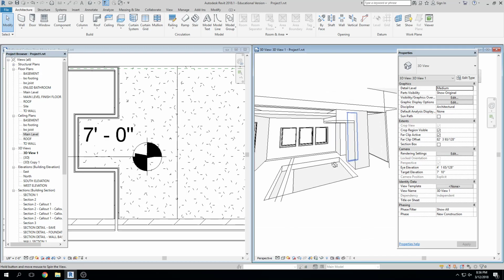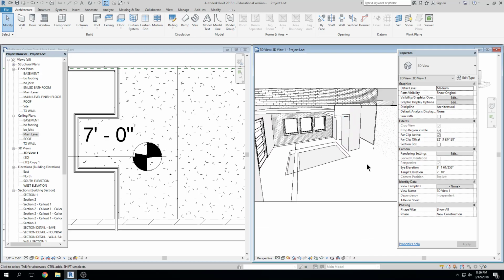Now, there's always a discussion on this, right? When you're working professionally, if there's not a detail being shown of that area, do we actually need to go in and create all those drop soffit walls, right? And the answer is likely no. When in a commercial building you have 10 stories and 400 conditions of soffits, the labor involved in drawing those and then making sure they remain consistent, coordinating them, you may not have to do it, right?